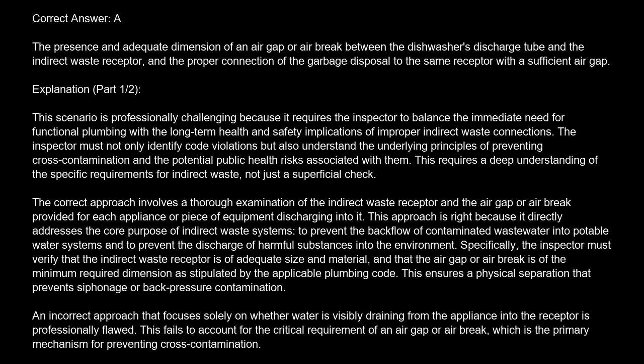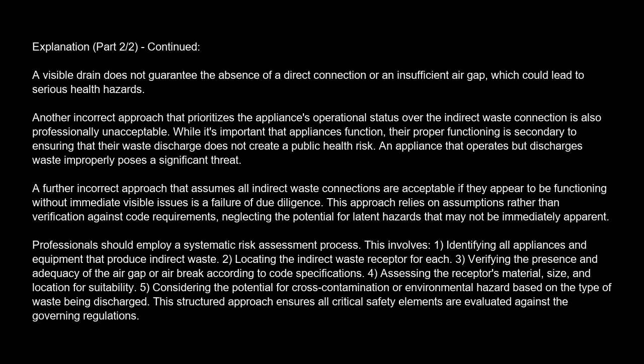An incorrect approach that focuses solely on whether water is visibly draining from the appliance into the receptor is professionally flawed. This fails to account for the critical requirement of an air gap or air break, which is the primary mechanism for preventing cross-contamination. A visible drain does not guarantee the absence of a direct connection or an insufficient air gap, which could lead to serious health hazards.